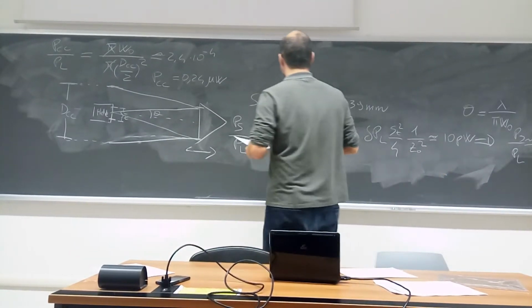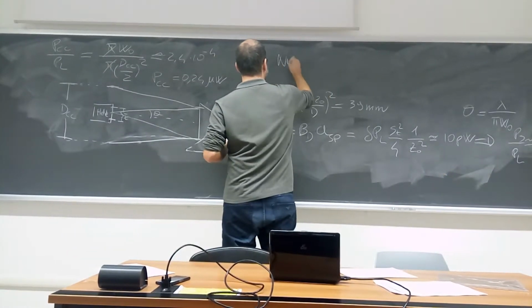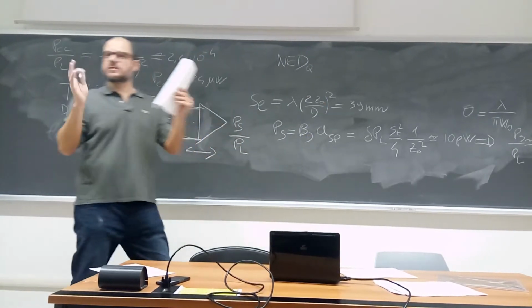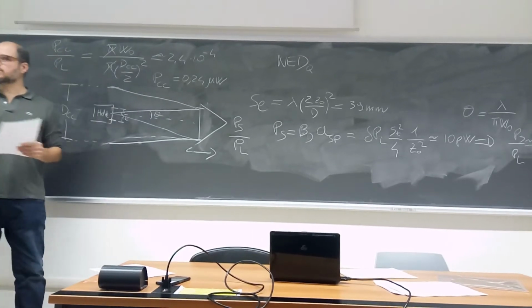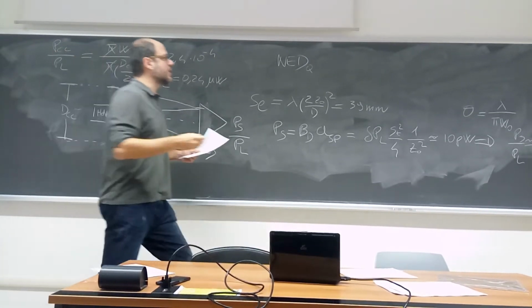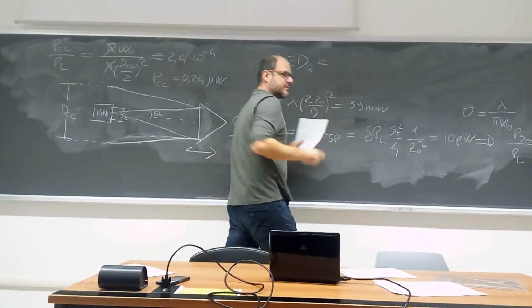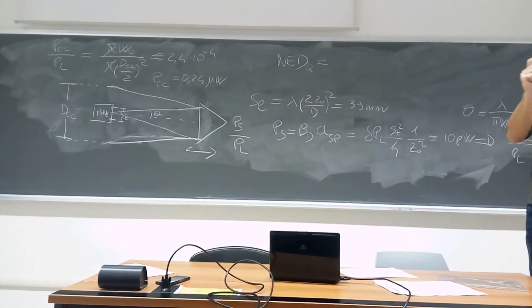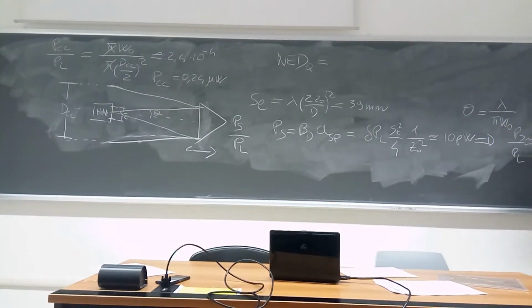Because in particular, we review also another definition of the noise equivalent displacement related to the quantum noise. We have used more frequently the relation that says that the noise equivalent displacement is proportional to bandwidth and photodetected mean current.